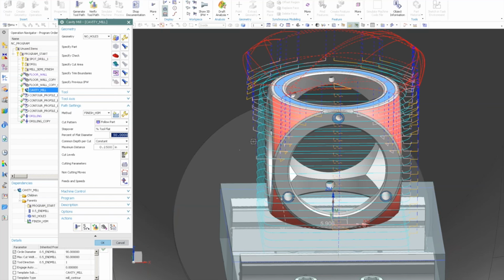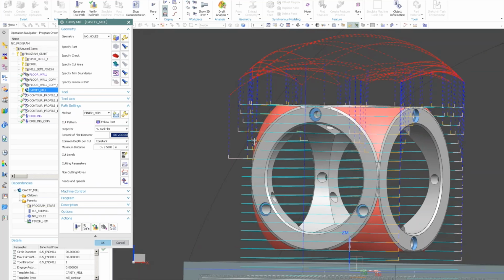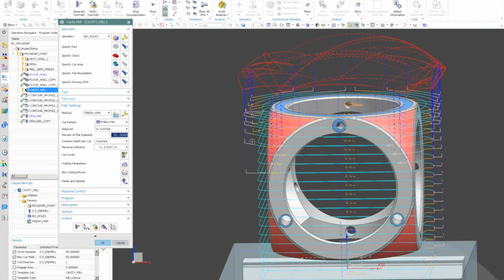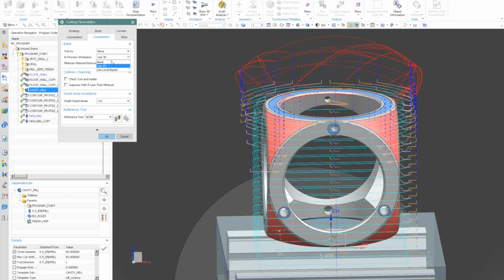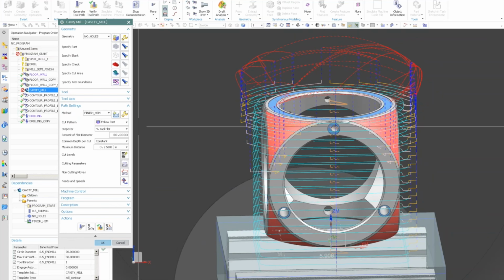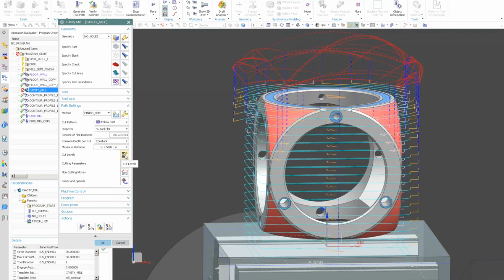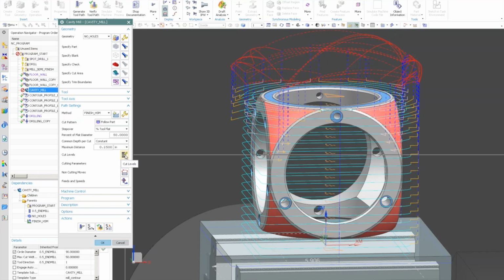And so it's not going to machine the very top level because it's already been faced. I tend to only use that as needed because it can add time to your toolpath. There are much easier ways to filter in this case that don't require scanning for the state of the stock. On this particular part, you can see it didn't take long.